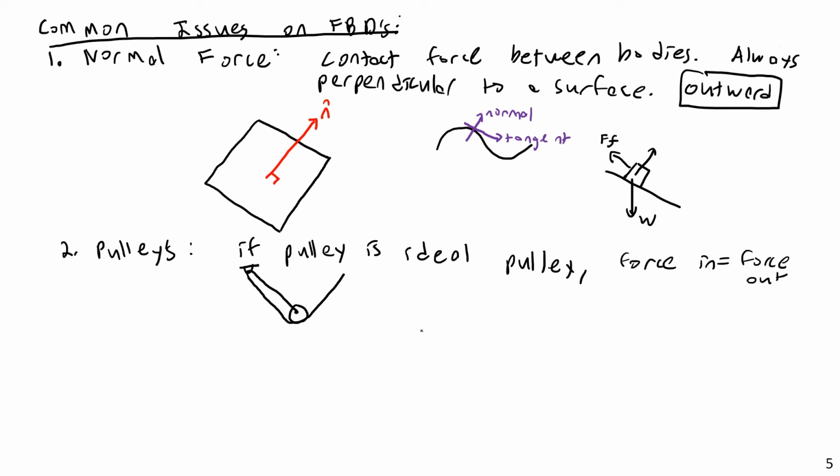And these are all ideal pulleys, and the way to set that free body diagram up is basically the same tension, but two times the tension here. Sometimes I'll see people try to do a T1, a T2, and a T3, and they don't quite realize that if it's an ideal pulley, the same force will be transferred all the way through the pulley, regardless of the number of loops. And then the idea was to work through the equilibrium therein.